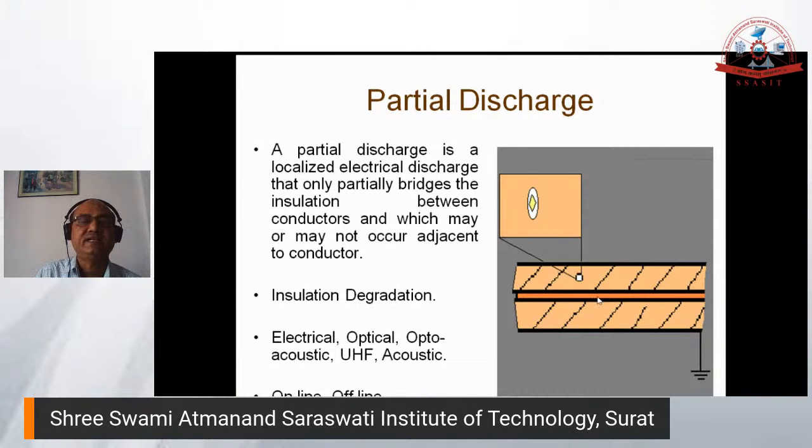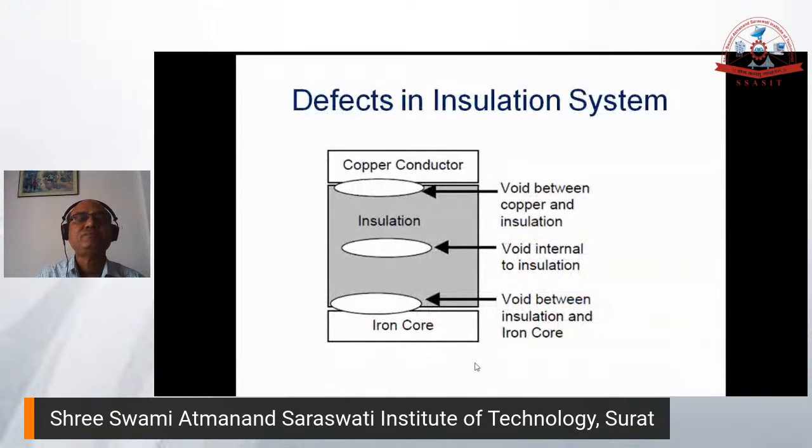So that is the insulation degradation. There are many techniques to measure PD: electrical, optical, optoacoustic, and ultra high frequency acoustic. And out of these different techniques, some of them are online, some of them are offline.